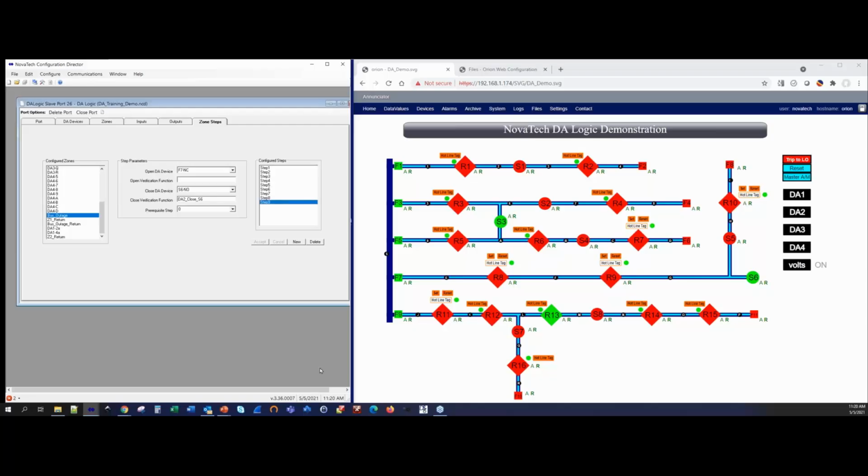So if you were simply going to have the DA system restore itself based on voltage inputs or other triggers that say, okay, it looks like the fault has gone away, go ahead and put the system back, you potentially are restoring a system that's in an abnormal state and could put your crews in danger.